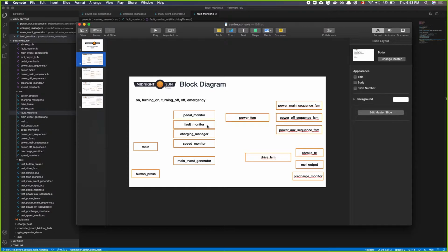But I didn't really want to put all of that information over here, because this is center console. I think if the battery faults, the battery should disconnect itself right away, and then let the rest of the car know that it has faulted, but that's it. I don't think center console should be a proxy for whatever fault handling message needs to be sent out. Because there are two different pathways.